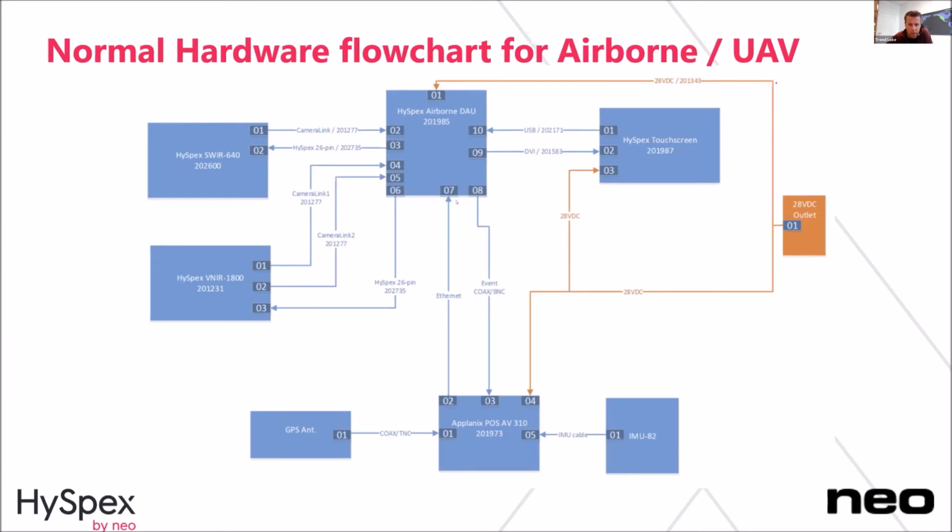Then you have communication, Ethernet for example, to the navigation system. You have a BNC that's sending the event from the frames that is timed on the navigation system. You have a GPS antenna connected on the roof, and you have an IMU somewhere, which typically you want to have as close to the camera as possible. Then you have a touchscreen interface to start and stop acquisition. Of course, that can also be triggered automatically from FMS or from TCP/IP commands or serial commands.